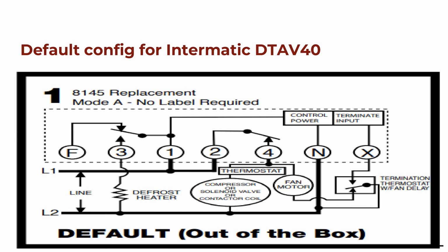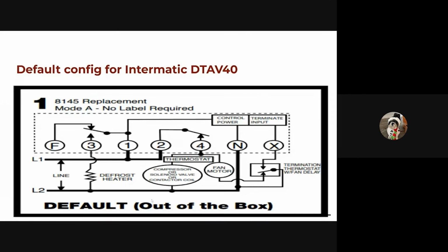So what's happening? Let me go back to this other component. There's this thermostat in the circuit. Let me see if that's changing position. What are the set points on that thermostat? Are they set correctly? If so, okay, well, are the contacts moving on that? And then you could diagnose this part and see whether or not maybe this part needs to be replaced, or maybe it's not installed correctly, or something to that effect.